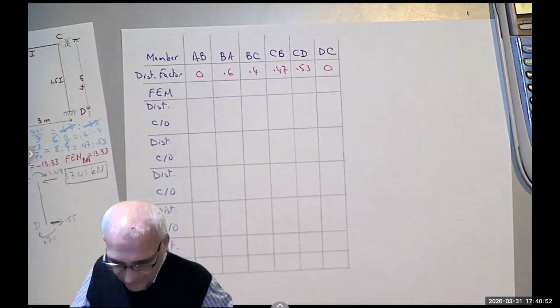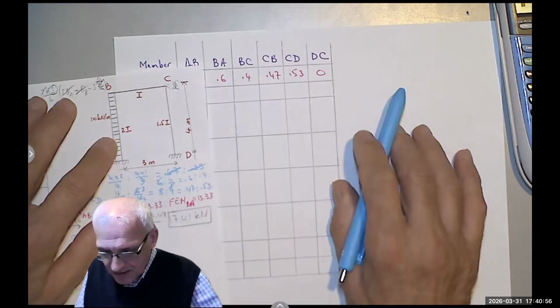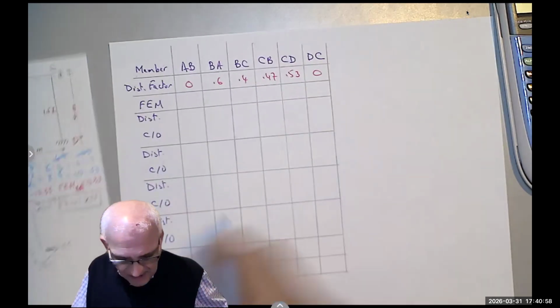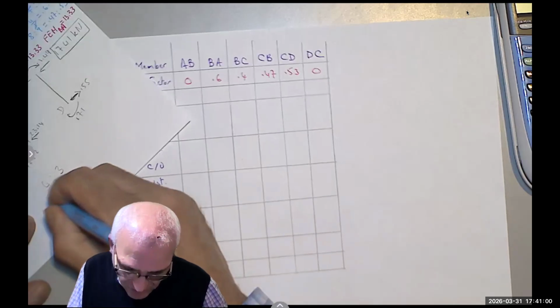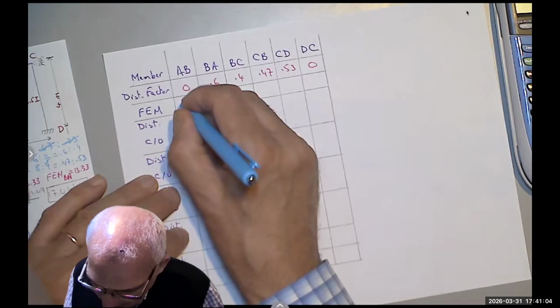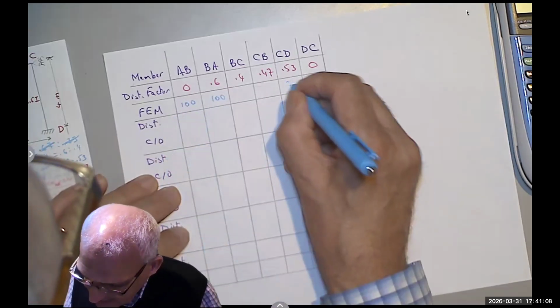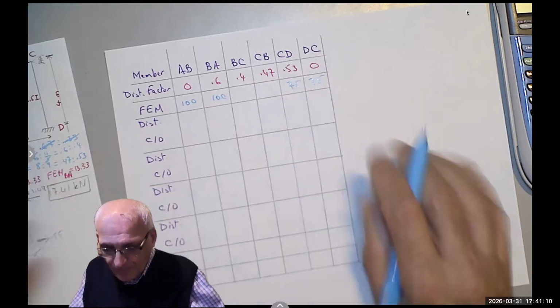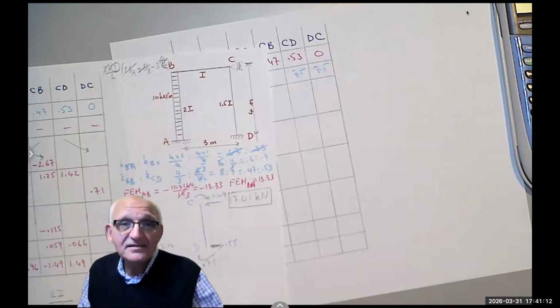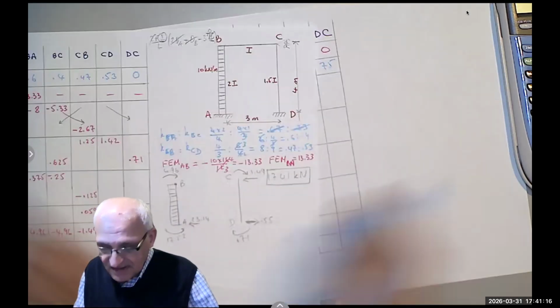So, for example, notice this one is the bigger one, so I can call this 100. So it would be a nice number. And this is 75. So I'm going to say 100, 100, 75, 75. So to both legs, you add a positive moment.